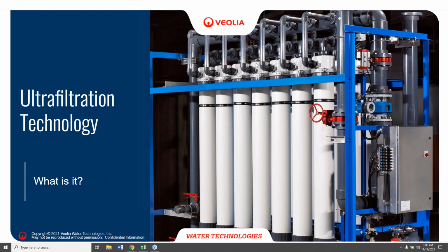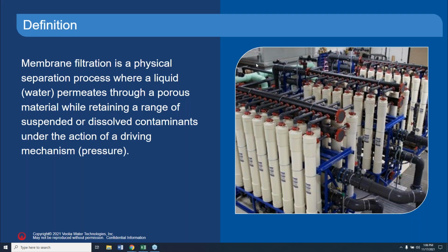So as we started, the most important place to start would be just to say, what is ultrafiltration, or UF technology, as we like to refer to it. Ultrafiltration really involves a pressure-driven separation of materials from a feed solution. The technology as we use it achieves separation through sieving and is used to remove particulate and microbial contaminants, but it does not remove ions or molecules of low molecular weight. That is one of the distinctions we do draw.